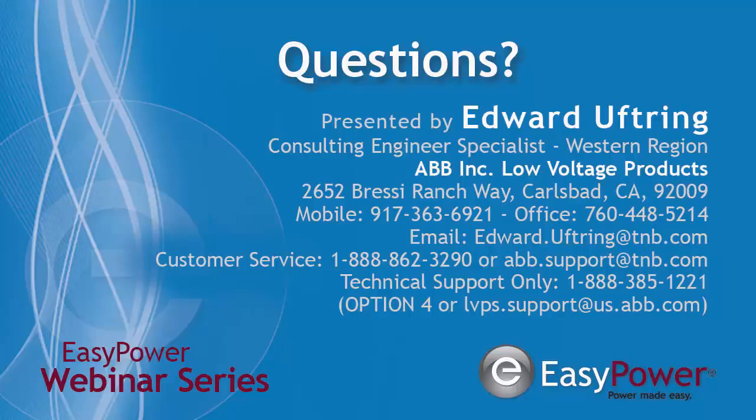The two curves in the L and the I is available because you are able to set one unit to have two separate curves. So you can have an L1 and an L2. This allows the breaker to, at some points, be set to a lower time delay when the L1 is activated, or you can set it to an L2 so you can switch the, if you will, breaker profile so that L2 has a larger time delay.